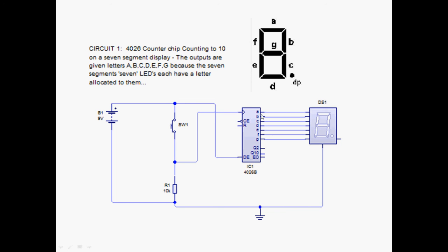So if you imagine, if we lit up channels B and C, I'd display the number 1. If I lit up D, E, G, B and A, I'd display the number 2. If I lit up all of them, I'd display the number 8, etc. Okay, so this may come up. You could make a steady hand game out of this as well. It would just show your lives lost as a numerical digit rather than LEDs lit up. Again, watch the Deca Counters video if you're unsure.